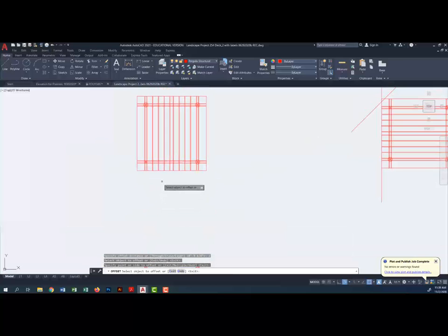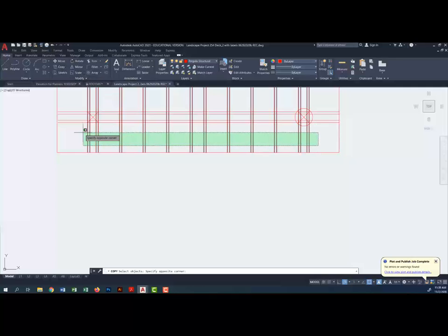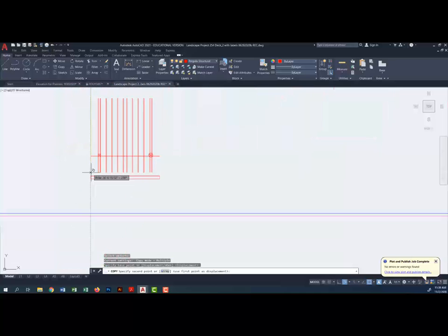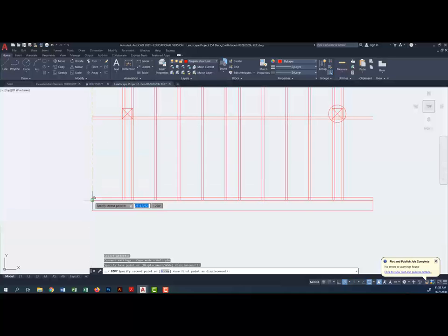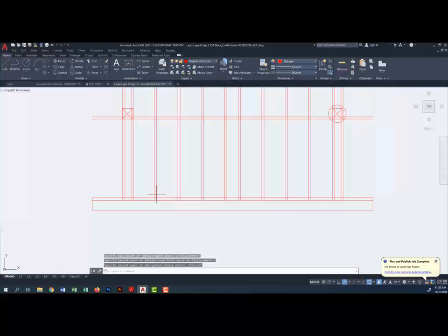And all I'm going to do here is copy all of this from endpoint down to this 2-inch location. Now, my ceiling joists, I'm just taking a reference look at my drawings here. My ceiling joists, I calculated them to be 2x8s. So I'm going to offset 7.25, this lower line up. And I've got my ceiling joists. You may not see them, but they're there.